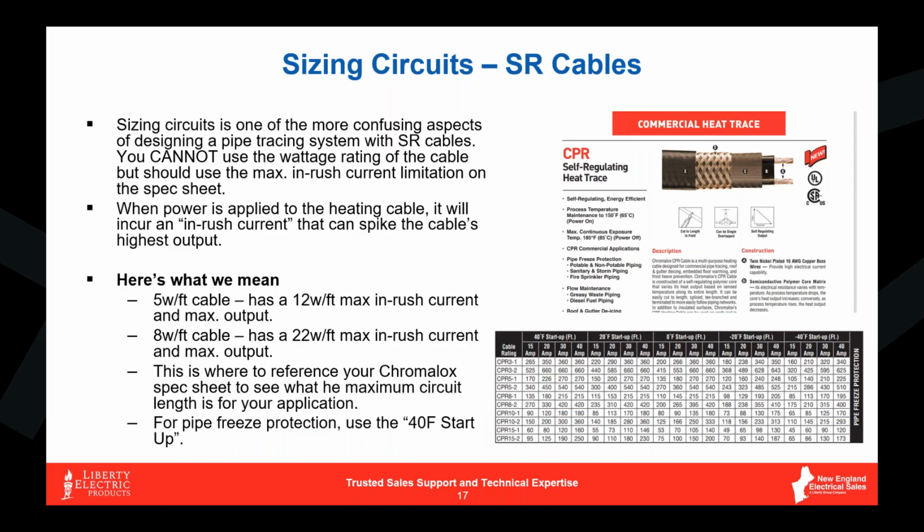So this slide is really the most confusing of the presentation, in my opinion. It goes back to how we size these circuits for self-regulating cables. I inserted a chart here that you would find on the Chromalox CPR cut sheet to give you an idea of what kind of resources are there for you as well. And this is what we're pulling from when you call us to ask us a question: what's our circuit length max when we're talking about, say, using a 20 amp breaker and I want my startup to happen at 40 degrees F, pipe freeze protection? Well, we can look on this handy dandy chart and tell by what wattage per foot cable it is.